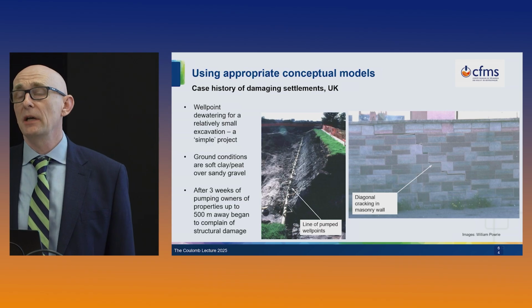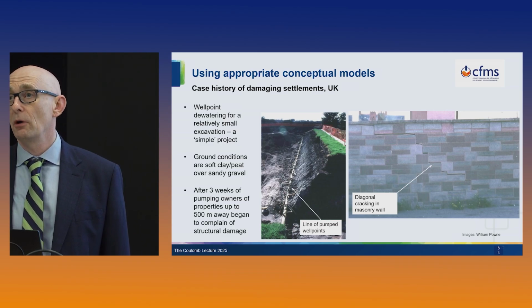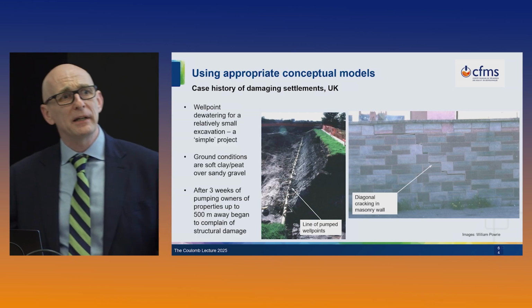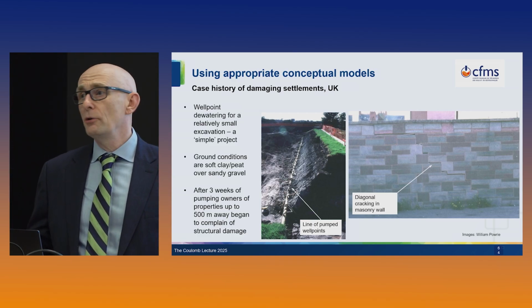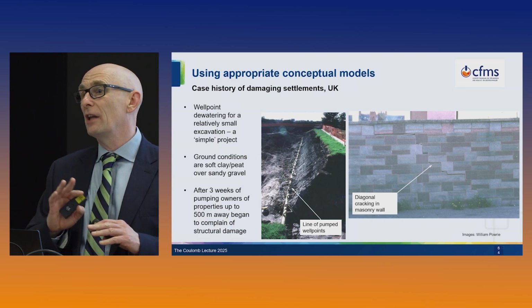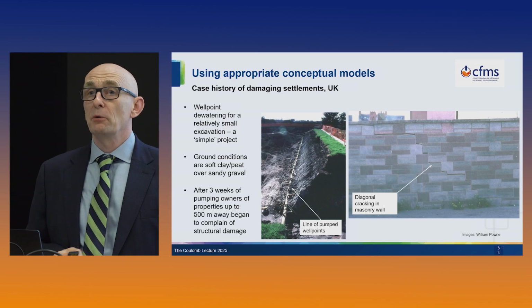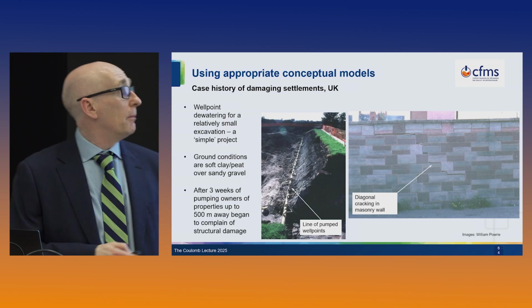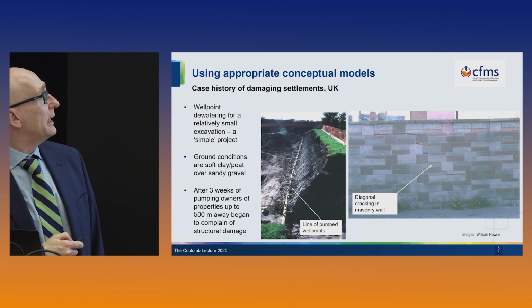It's a project in the UK where there were damaging settlements when groundwater control was carried out. These cases are actually quite rare when you get genuine damaging settlements, so it's worth a discussion. It's quite a small, simple project, and I'm fairly sure that at the time it was done there was very little design and certainly no conceptual model. It was for a water project where a fairly modest excavation was being made, and the ground conditions were a few metres of soft clay and peat over sandy gravel.